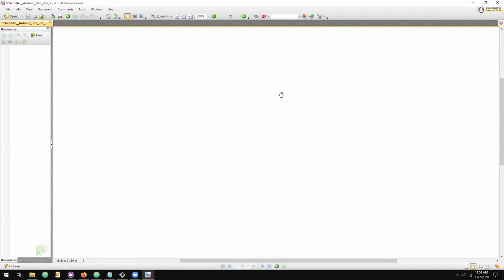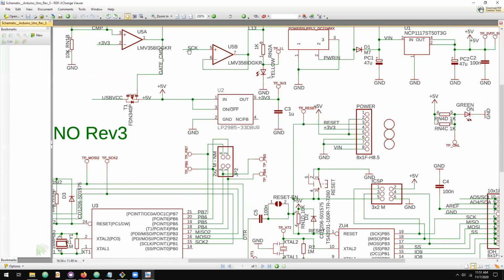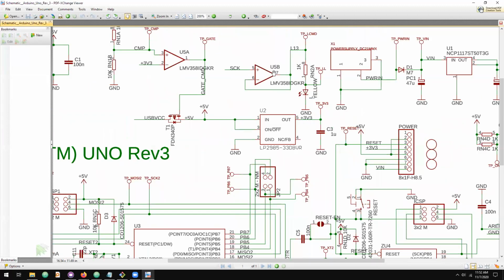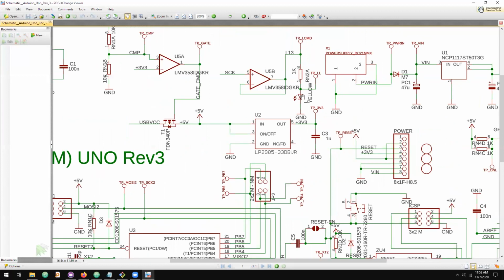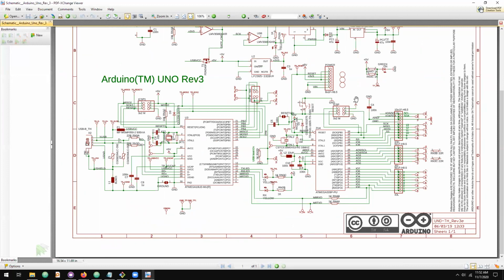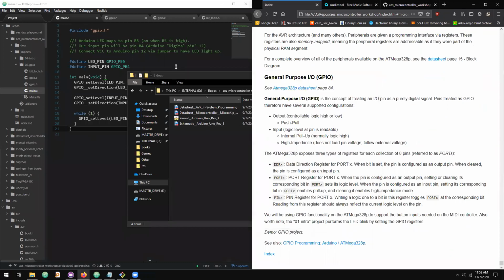Oh, a minute. Here it is. It's not shown directly, but this SCK net. So PB5 connects to the SCK net, and the SCK net connects to, I don't know why I'm blanking, a buffer that drives this LED. So this is the Atmega 328P, and here's all of the surrounding hardware on the printed circuit board. So that's also in this documentation directory. But back to the code.